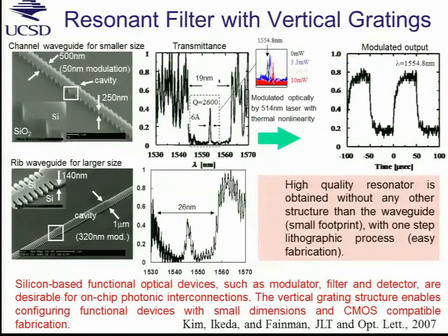So we made these photonic crystals, and we introduced the quarter wave offset to make a defect. And then you clearly see this measured 19 nanometer stop band with a transmission line in the middle, and the Q is not that high, but it's above 3,000. By the way, for telecom applications, if you want high bit rate, you don't want high Q. The photon lifetime has to be shorter than the modulation rate. So that's something to keep in mind.